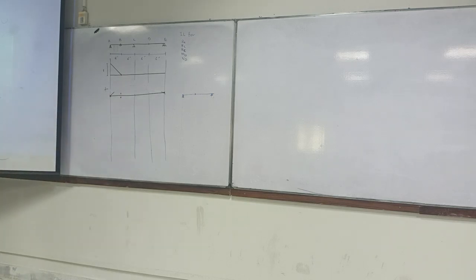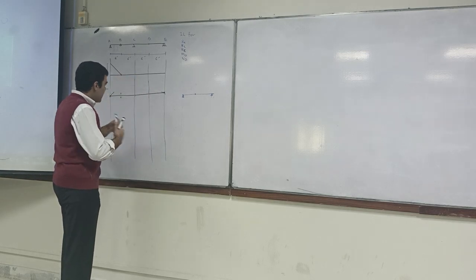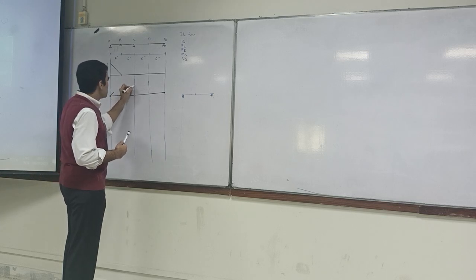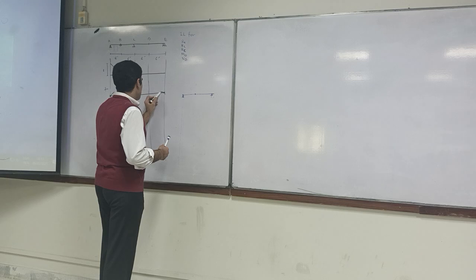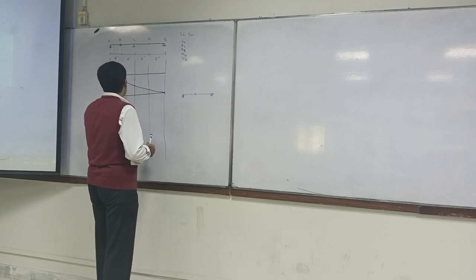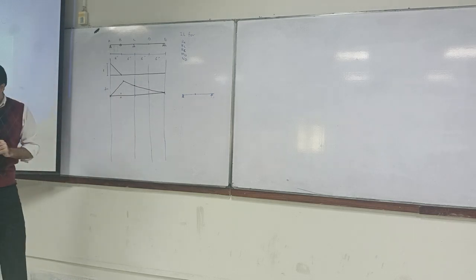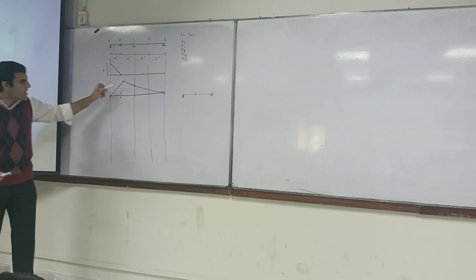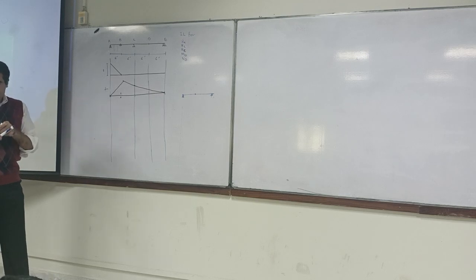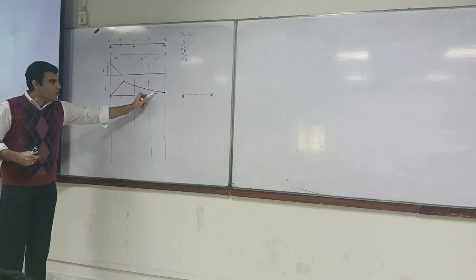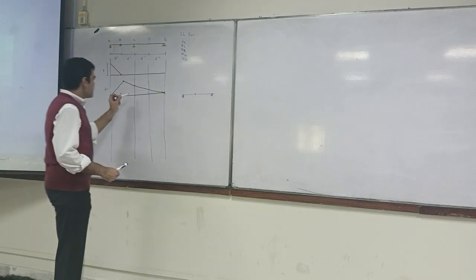In the diagram, we will have it again 1 over here, and this will again go like this, but this is the only place where it can bend. It's not bending, it's actually zero movement, so it can rotate with respect to the other member. Is that okay or not? This is going to be a straight member because this is all straight member. There is no internal hinge. So this is going to be 1.